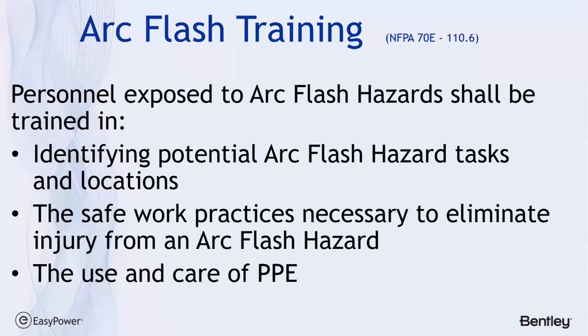And training people as to what those terms mean and when to recognize an abnormal situation, and in that case, stop what they're doing and inform management of the situation, can save a lot of mistakes and errors that are caused by the lack of awareness. So it's important to identify potential arc flash, ensure that safe work practices are necessary, and then as a last line of defense, know how to select PPE and to properly use it.